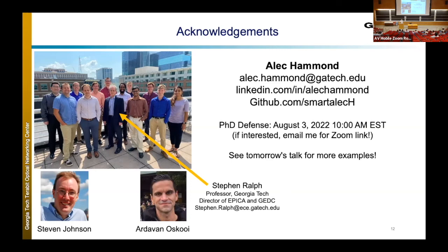So in this particular example, I might say, hey, the performance I'm getting at the end of the day, I only got 46%. I bet you, like you said, Ryan, it's because the design region is too small. There's not enough room for wave action for us to maximize that. So I'm going to bump it up to maybe 4 by 4 microns. But I also know that that's going to take slightly longer in my cluster, so I need to make sure I have enough credits. You know, there's that calculus that always needs to be considered.